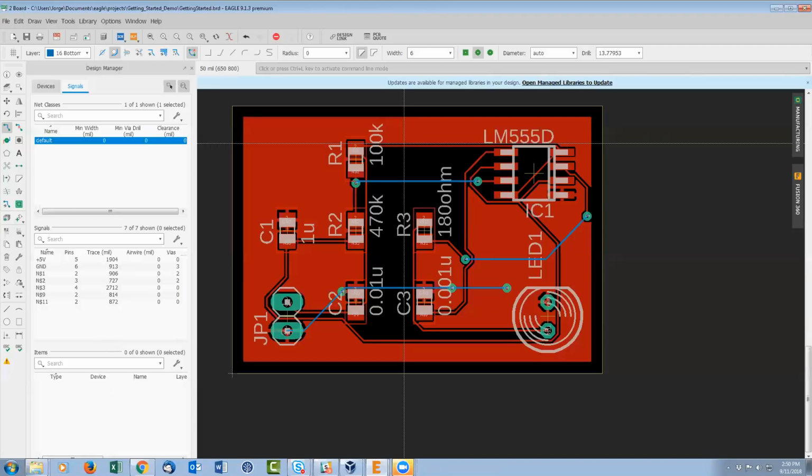It is one of the more painful of the errors and the issues that can come up with Eagle. So it's best to just avoid it in the first place. And the way you do that is keep your schematic and board always open together. Very key point. Okay, so that's the schematic, that's the board.